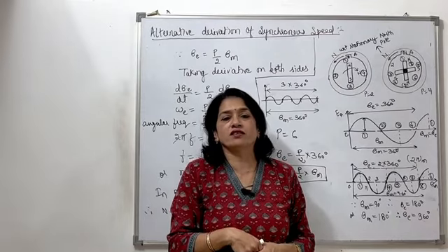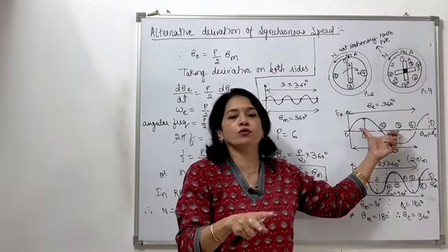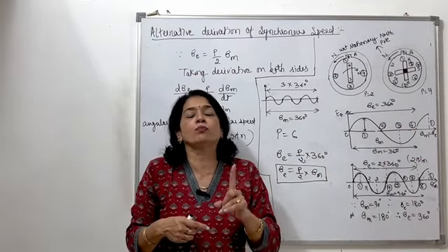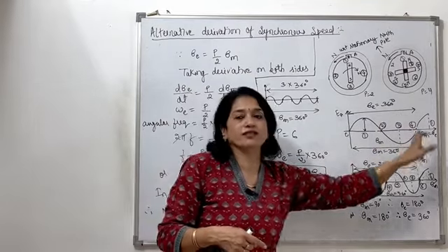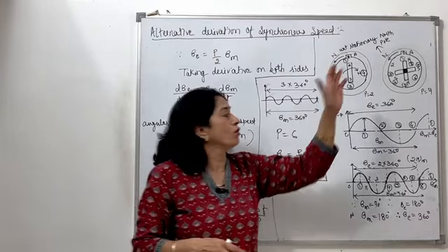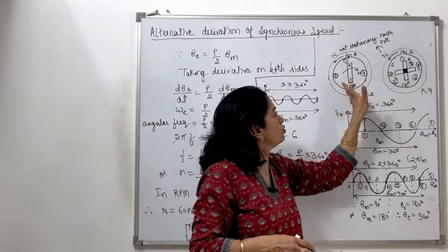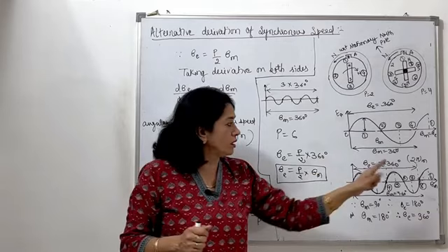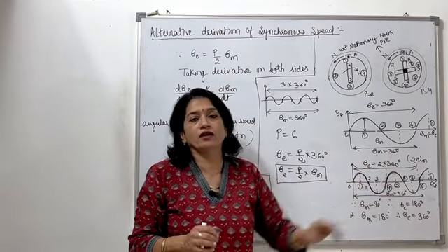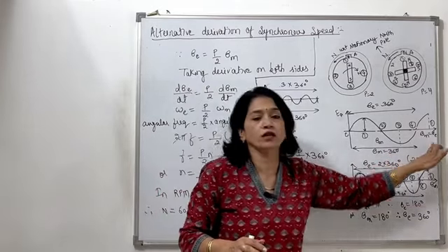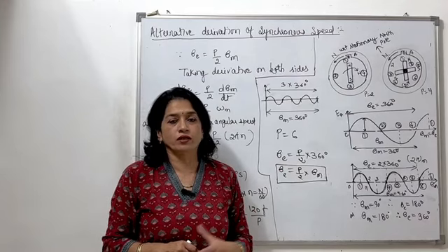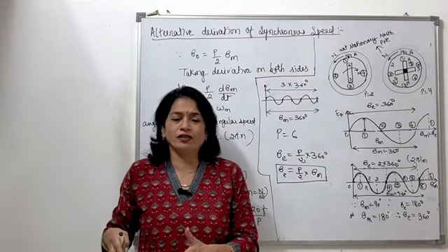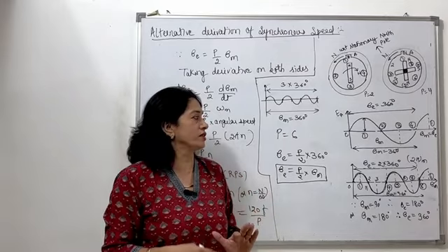traces the 360 degree, in the same manner in two pole machine, conductor would be having the induction of one cycle or 2 pi angle, tracing electrically also, from here 1 to 2, 3 to 4, and then again to 1, that way. What does this mean? Here it means electrical angle and mechanical angle are exactly same. So I wrote here theta m is equal to theta e, because both are tracing the same angle, mechanical 360 degree and electrically 360 degree.